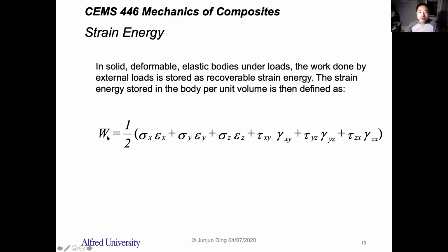Okay, so the work equals 1/2 times normal strain times normal stress in the x, y, z directions, plus shear stress times shear strain. Those are three different units.